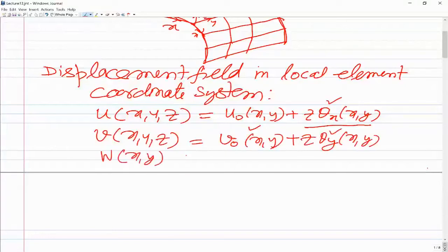So now we need to use these terms, and you keep in mind that these terms will also be needed when we are solving problems involving large deformation, or if there is a bending stretching coupling. So the mid plane, z equal to 0 plane, has got in plane displacement, so then you have to include u naught and v naught.